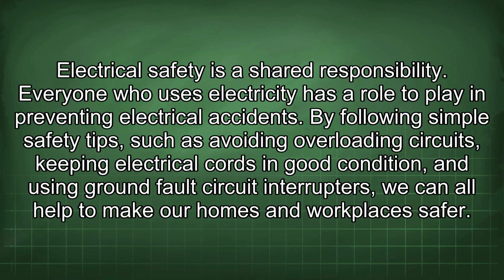Electrical safety is a shared responsibility. Everyone who uses electricity has a role to play in preventing electrical accidents. By following simple safety tips, such as avoiding overloading circuits, keeping electrical cords in good condition, and using ground fault circuit interrupters, we can all help to make our homes and workplaces safer.